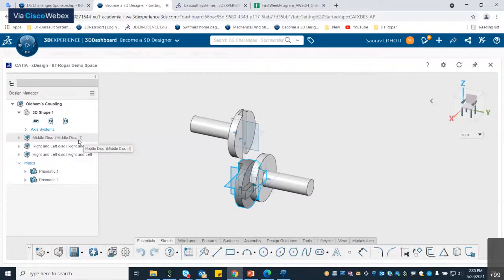First you have to create a fixed mate, because if no part is fixed, the mates are not going to be applied. One part needs to be fixed. According to that part, all the mates are applied, or components move according to that fixed part. So make sure that one part is fixed. At the end, after completing the assembly, just remove that mate, so it will not affect.